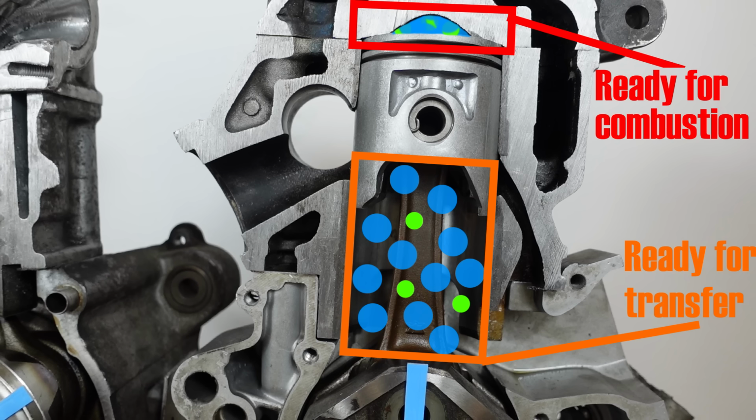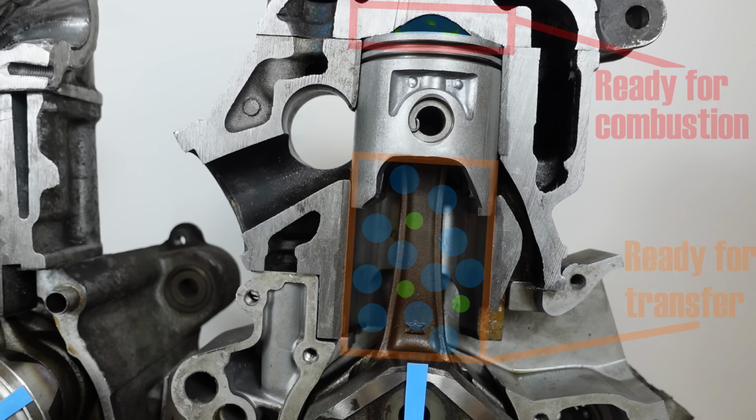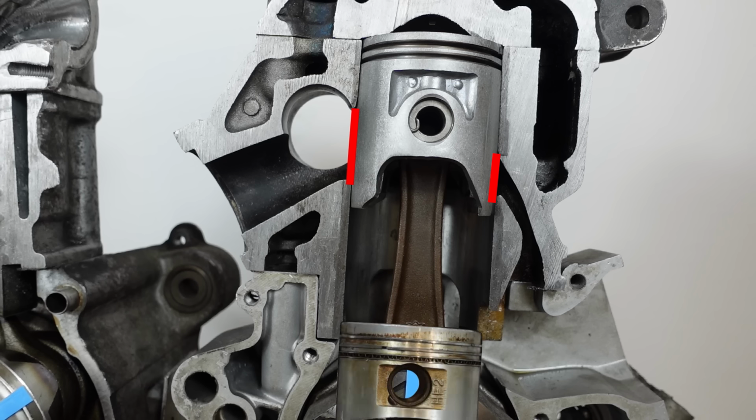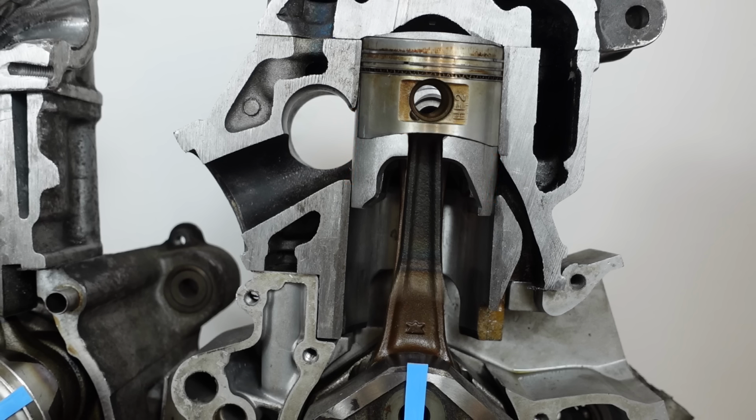The two-stroke combustion cycle and design also explains why the two-stroke piston is much longer than the four-stroke piston. It must be long enough to keep both the transfer and the exhaust port blocked off as it approaches top dead center. If the piston were shorter, exhaust gases could enter the area below the piston, but more importantly, the fresh intake charge could also escape out the exhaust port with the piston at top dead center.